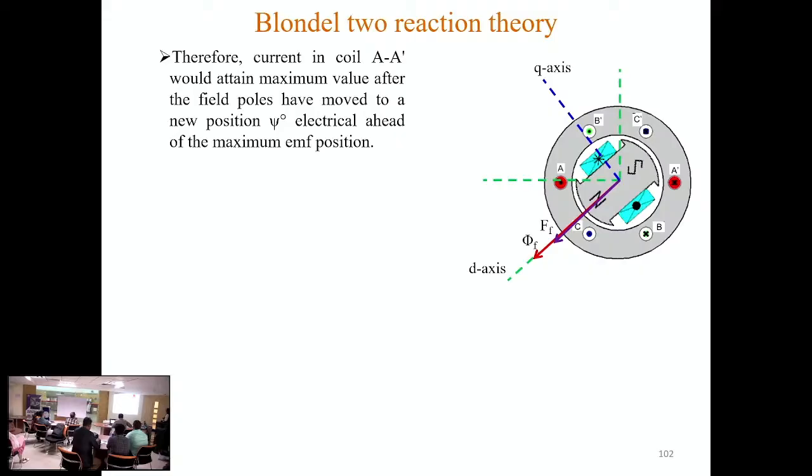After the earlier situation, the N pole and S pole have moved by this angle psi, the power factor angle for this case, and now the conductors A and A dash will have their maximum current, not the EMF.